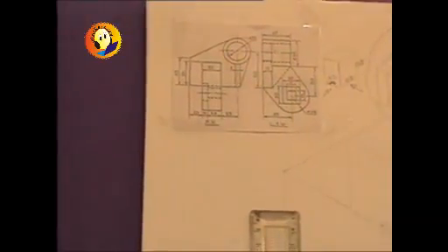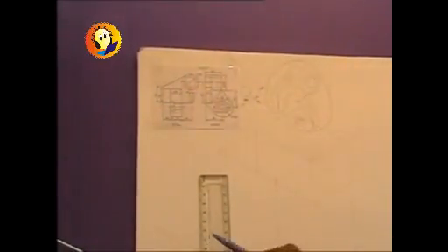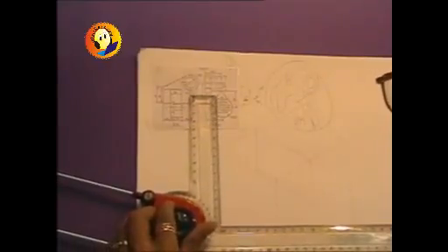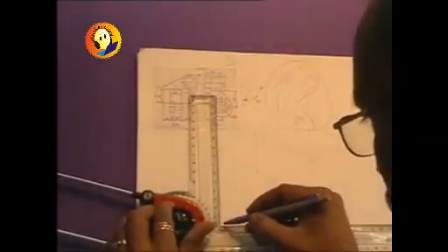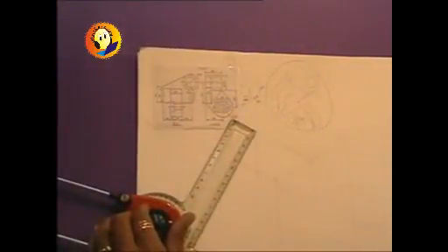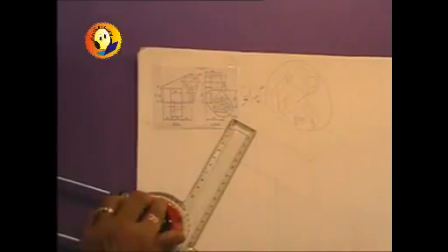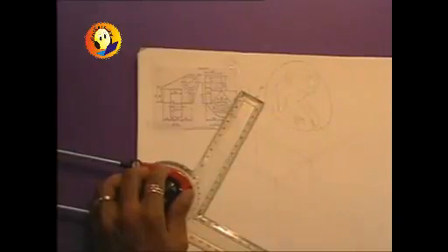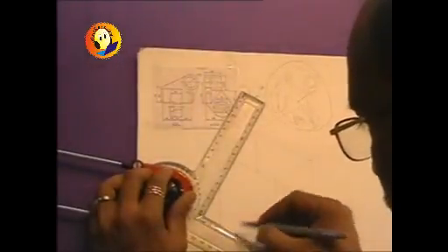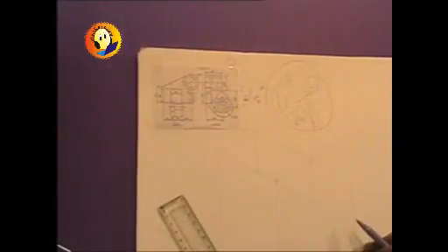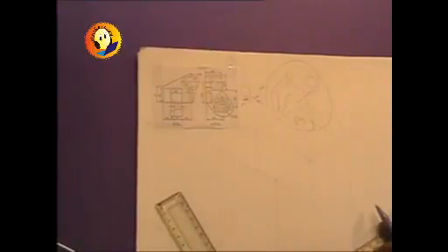So if we go back to our figure, then from top I am required to measure distance equal to 85 to get that particular point, and then distance in this direction is to be measured, which is 15 millimeters, so that I can easily complete the box which accommodates the plate portion of the given object.